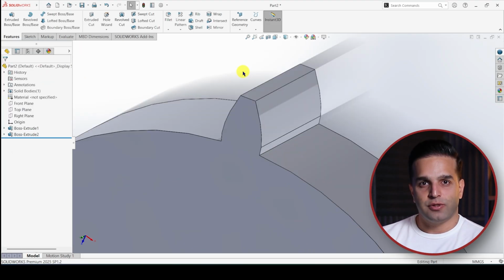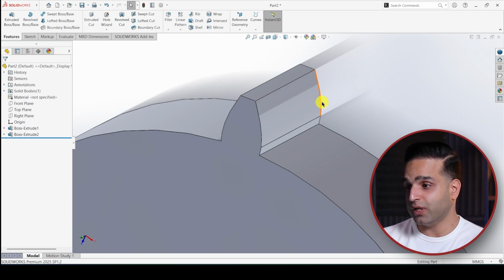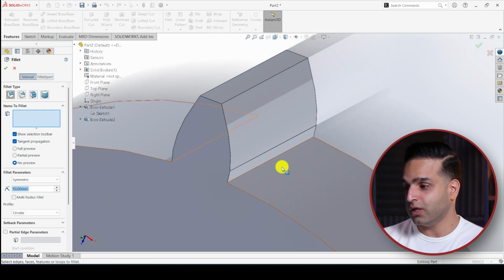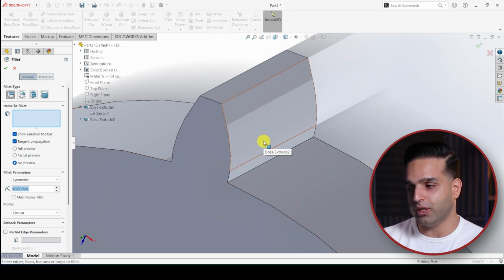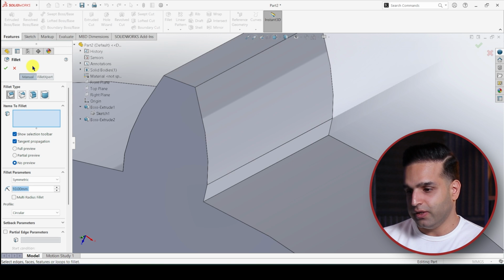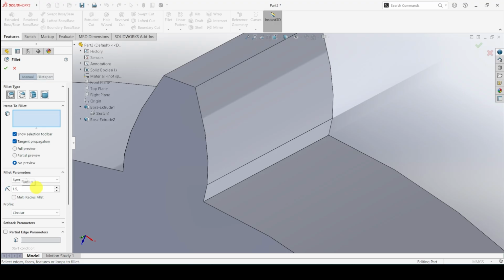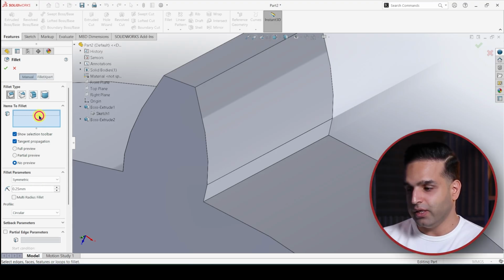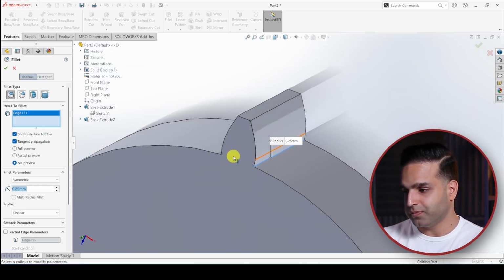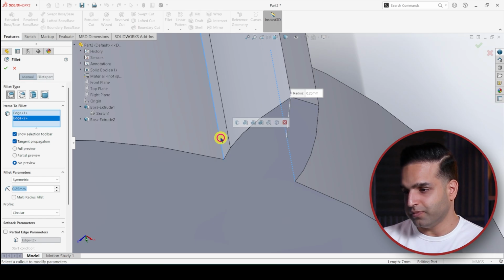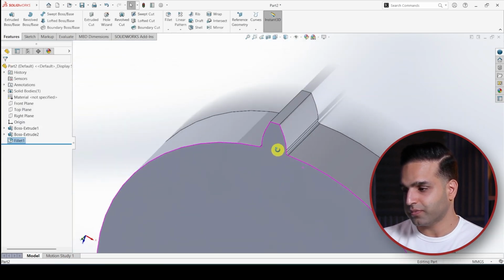The reason that I extrude the tooth separately from the body is that I want to generate 28 other ones, and before that I need to apply a fillet at the line contact between the tooth and the root body. So select the fillet, and the amount of fillet is 1/6 of the module. For the items, select this one and this one, and then confirm it.